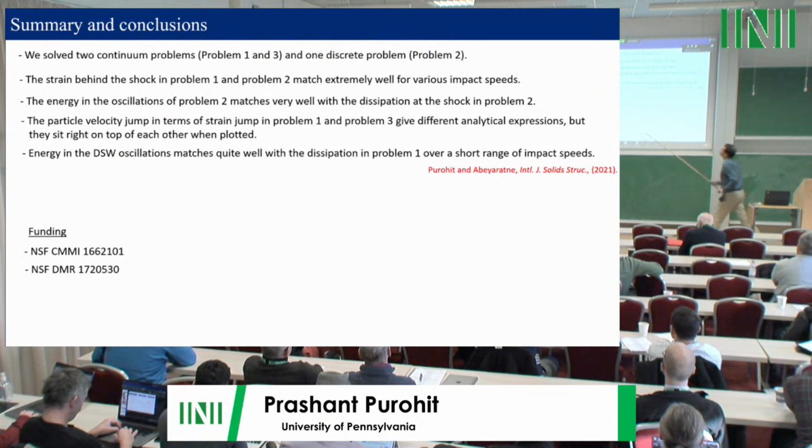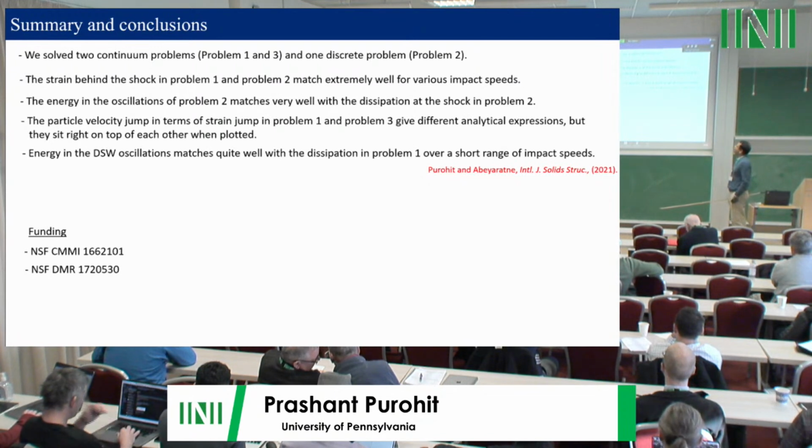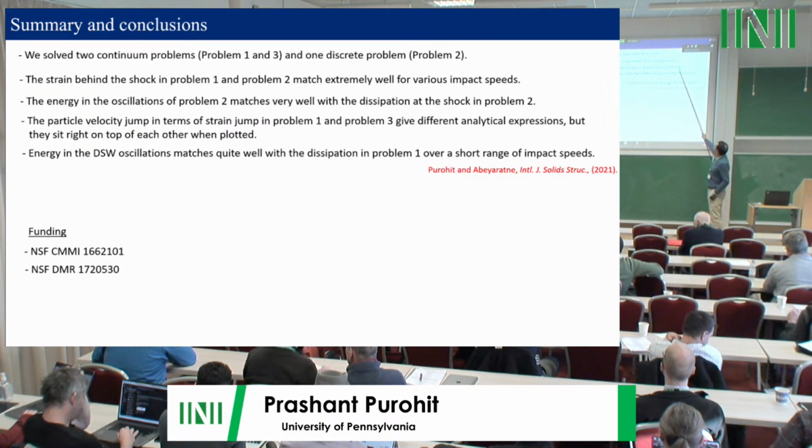That's it. We solved two continuum problems, problem 1 and problem 3, and one discrete problem. We showed that the strain behind the shock in problem 1 and problem 2 match extremely well for various impact speeds. The energy in the oscillations of problem 2 matches very well with the dissipation at the shock in problem 1.